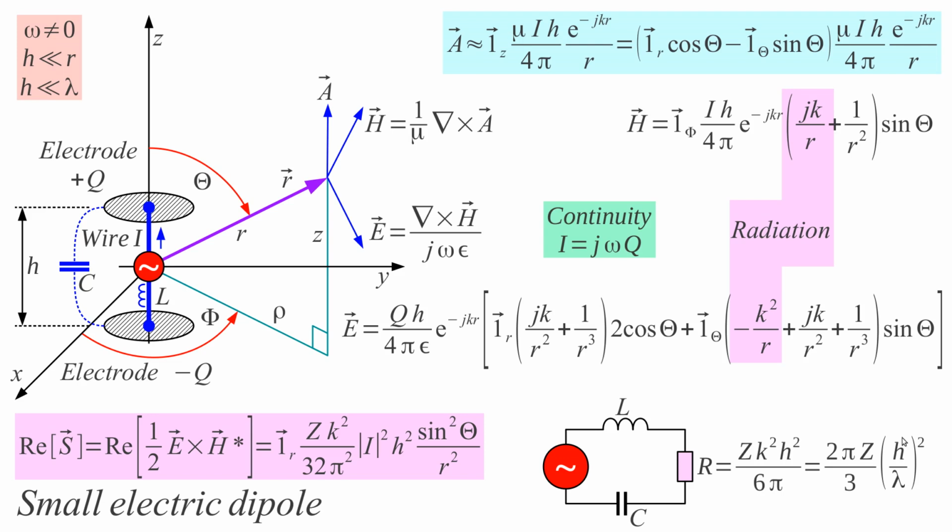So this h over lambda was a very small fraction, further squared. So radiation resistance was very low. These transmitters were very inefficient because of losses, especially in the coil here. And the production of radio waves with a spark was also an inefficient transmitter, so an inefficient antenna coupled to an inefficient transmitter. So everything went wrong here.